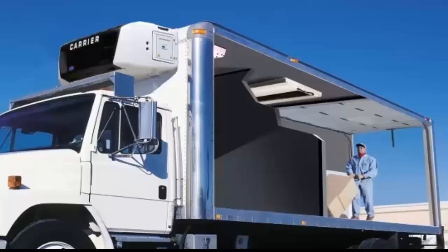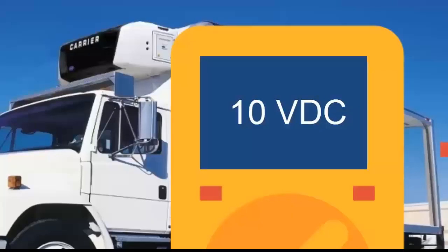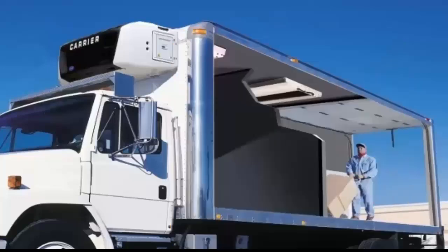5. Low battery voltage. This fault is identified with code AL4 and occurs when the battery voltage drops below 10 volts DC, affecting system performance. This could be due to poor connections or a discharged battery.